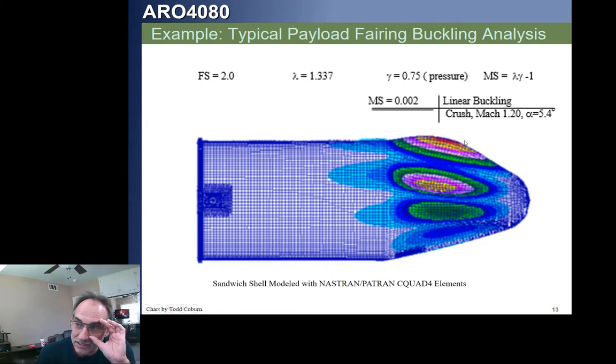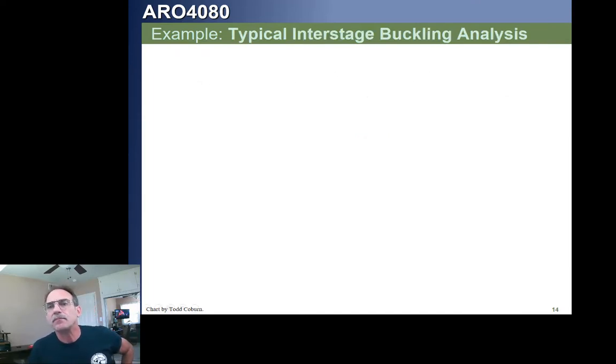Whenever you look at displacements, whether it's a dynamic model or a static model, usually it'll look like the structure is moving all over the place. That's because they show the displacements usually with a factor of 100 or even 1,000 times the actual displacement. Otherwise, you wouldn't see it. They wouldn't look like it's doing anything. So this allows us to see with our naked eye how the structure is responding. We can gain insight about the problem from that.